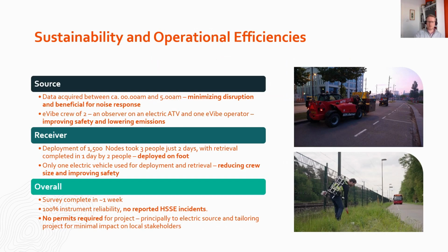Now, just to look at some of the results from the project and starting off with the operational efficiencies and sustainability. So for the source effort, the seismic profile did run through the city centre. So a lot of noise was expected from traffic and also railroad, which ran close to the survey itself. Therefore, to improve personal safety and also minimise this external noise, it was decided that acquisition would take place at night between midnight and 5 a.m.